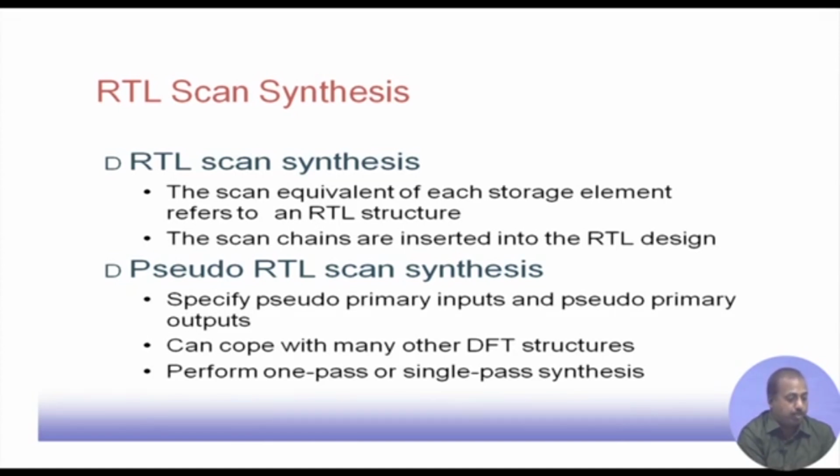So, what is pseudo? We can specify some of the inputs to be pseudo primary inputs and pseudo primary outputs, and only for those flip flops or those inputs outputs, it will try to put them onto a scan. So, it is actually going towards that partial scan.